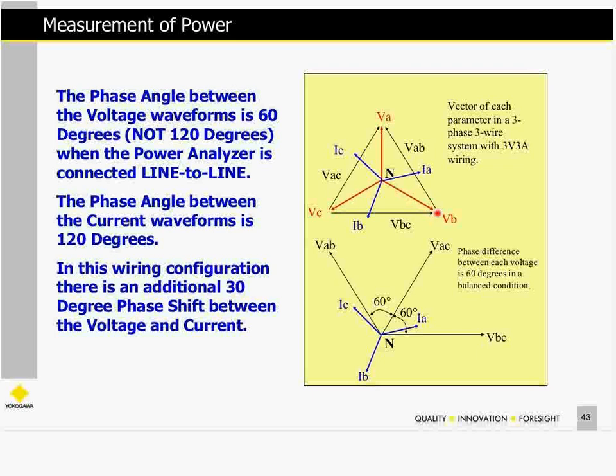So the way the meter is connected is in a delta, okay, configuration. So all 3 voltages in here, the way the meter sees the connection is in a delta. And these voltages on a balanced system are 60 degrees apart, not 120. And then if this current comes back up in phase, to say the red line here, you'll see that the current has an additional 30-degree phase shift between that current and that voltage.